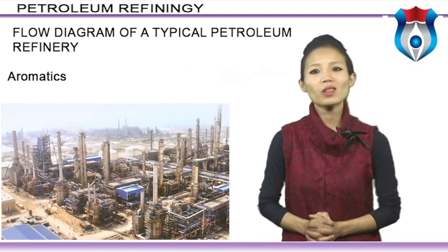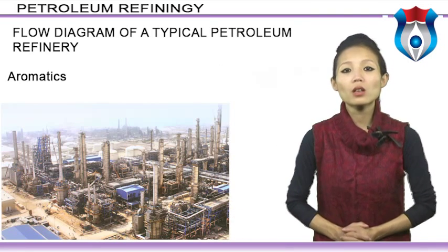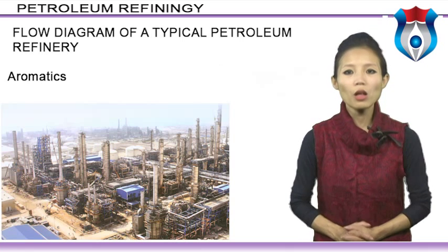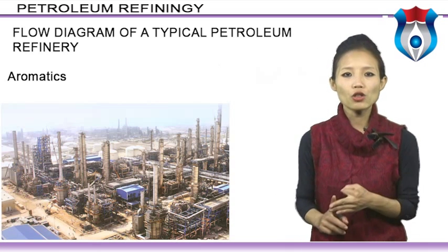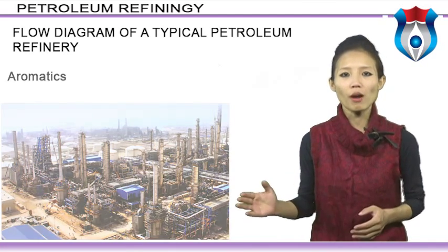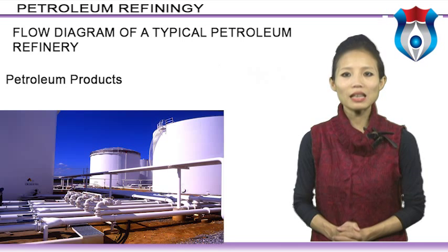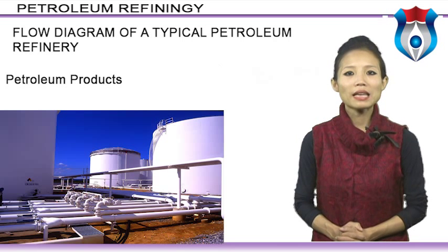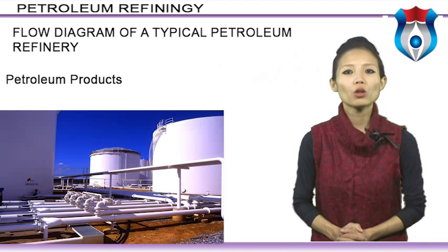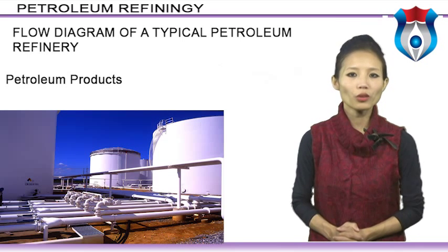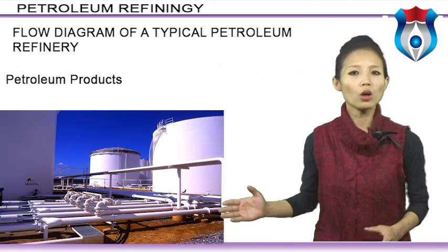Every refinery begins with the separation of crude oil into different fractions by distillation. The fractions are further treated to convert them into mixtures of more useful, saleable products by various methods such as cracking, reforming, alkylation, polymerization, and isomerization. Petroleum products include refinery gas, ethane, LPG, aviation gasoline, motor gasoline, jet fuels, kerosene, gas or diesel oil, fuel oil, naphtha, white spirit, lubricants, bitumen, paraffin, waxes, petroleum coke, and other oil products.